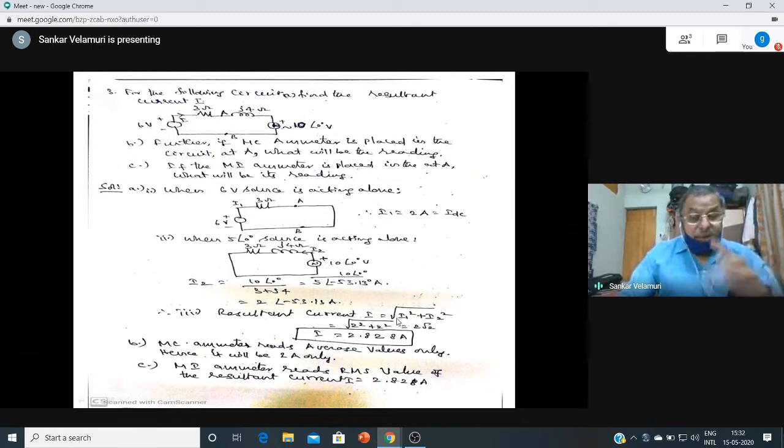If you want, we have to verify it practically also. That is circuit behavior, that is component behavior. So you can verify that. I is equal to the square root of I0 square plus I1 square plus I2 square, but I1 is a DC component here. It is not the fundamental component notation. I1 is equal to 2 amps, I mean to say here, for this particular one the notation is slightly different. I2 is the RMS value of the current. So the square root of 2 square plus 2 square is 2 root 2. That is 2.828 amperes. Okay, you will not find this in any textbooks.